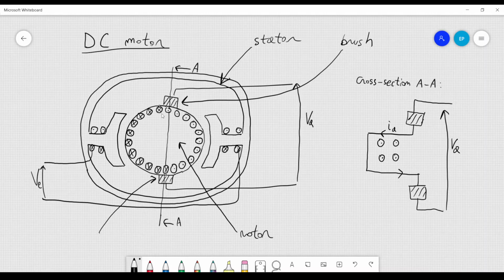And the other fundamental components which allow the rotor to move are the coils, which are drawn in here. Let me circle in red the coils. And some of them you can see that are different from the others. So, for example, this one here has a dot inside the circle. That means that the charges inside the coil are moving outwards of the coil. So they are moving outwards, and then they are going to be connected with this other part of the coil which has a cross inside. And that means that the charges are entering the coil.